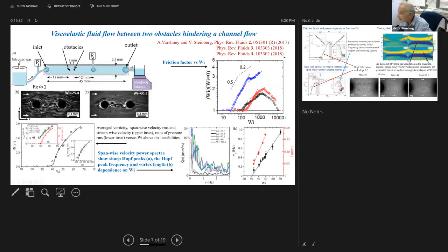This is the biggest, three different elasticities. Elasticity is the ratio of Weissenberg to Reynolds. Reynolds is small, Weissenberg large, and you can see that with the largest elasticity number we have this strange behavior. We didn't expect this: drag reduction and re-laminarization. Then with smaller elasticity we still have a drag reduction regime, and with small elasticity, of order 11, we don't have this part.